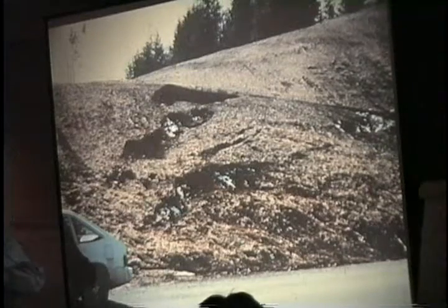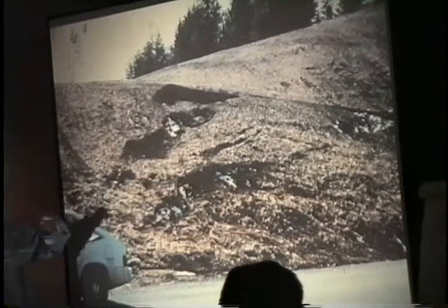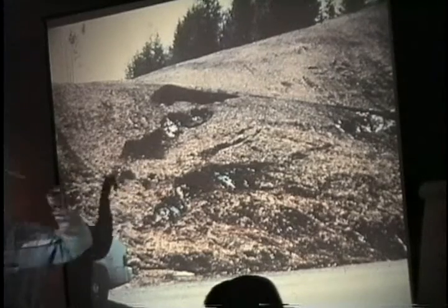Robin showed that you can take what you call live stakes and drive them into the slope, and it would make the slope more stable. These were live plants. It's like putting in a root structure, but you're putting in pins. And if you pin it back, you're taking this weaker material and you're reinforcing it.